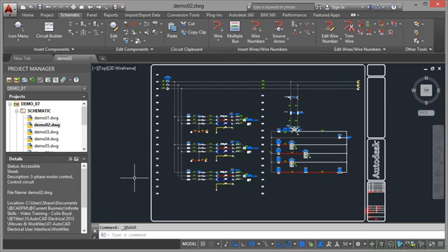Creating backup files when you're using AutoCAD Electrical is very important. My suggestion is that you always back up the entire project folder, especially if you're working in a server client environment in an office, for example. Now, AutoCAD allows you to back up every drawing that you save.